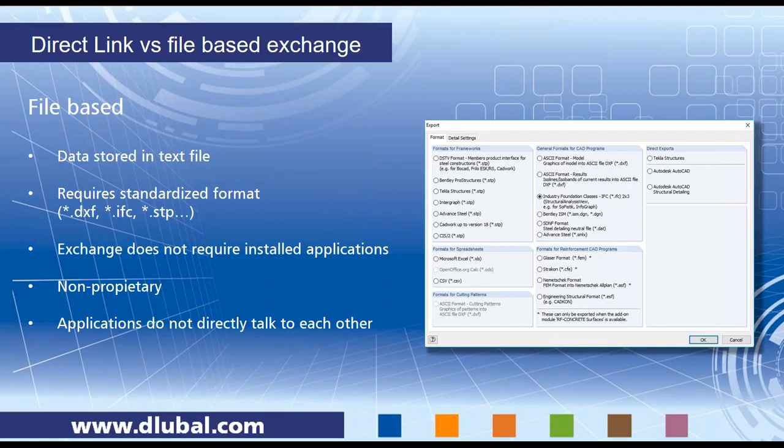Depending on the specification, what entities and what kind of objects these formats provide, we may or may not be able to write our data into these files. IFC, for example, has no way to write nonlinear supports or information about load generation standards, a lot of information we just have in our software.